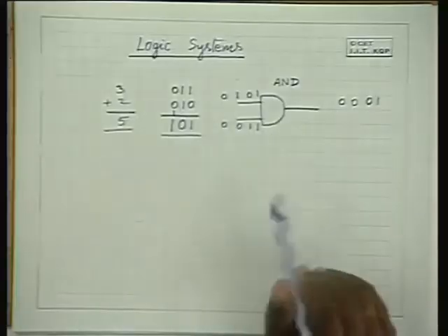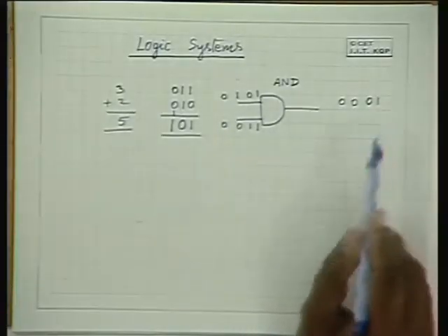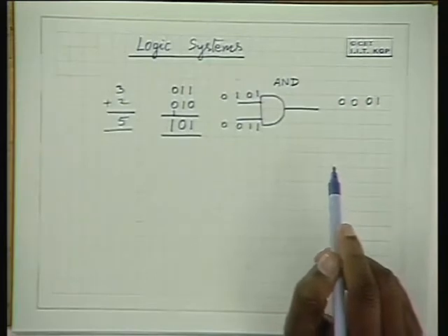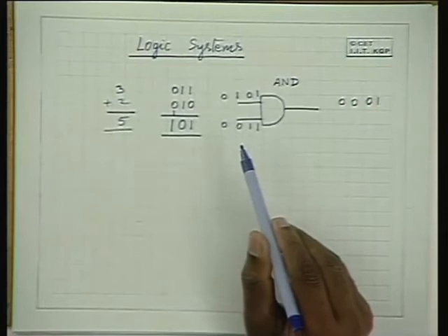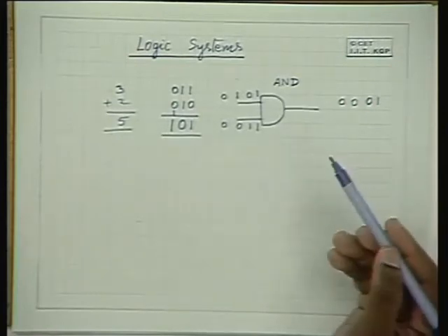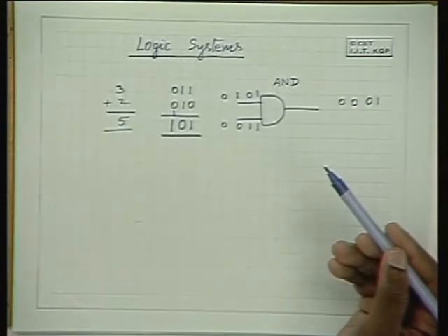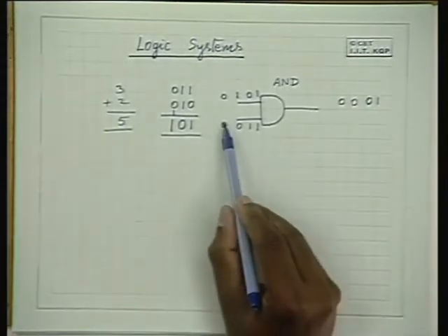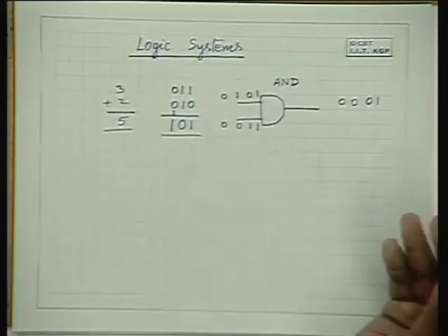Okay. So, that means it acts like a multiplier. It is a 2 binary bit multiplier. 1 into 1 is a 1 and 1 into 0 or 0 into 0 is a 0. So, what are these 1s and 0s? So, these are voltage signals. Okay. So, for instance, you may designate a 0 by approximately 0 volts, and you may designate 1 by an approximately 5 volt signal.